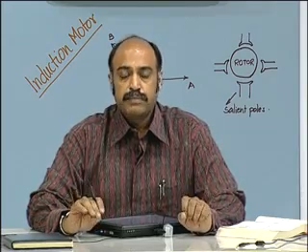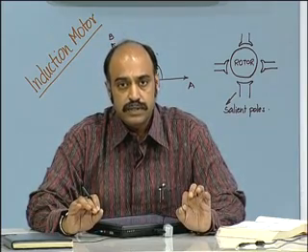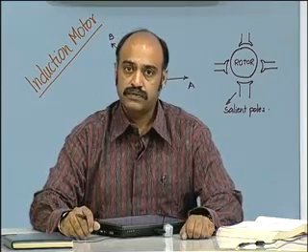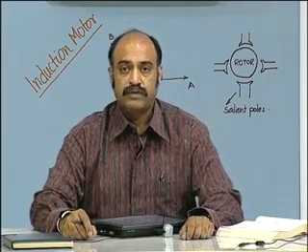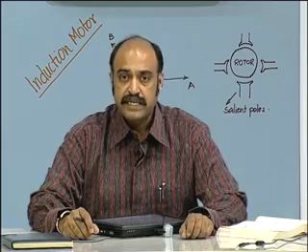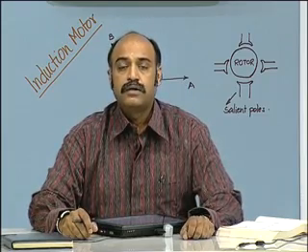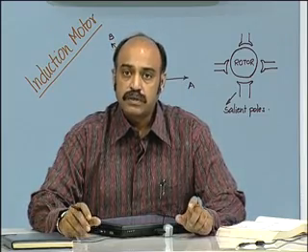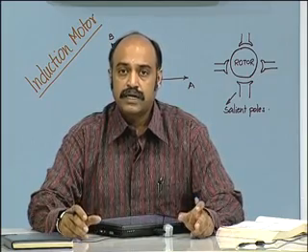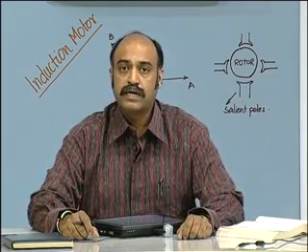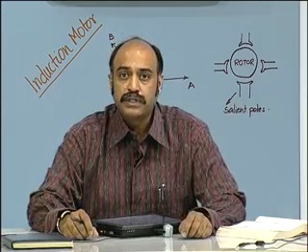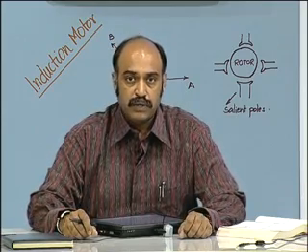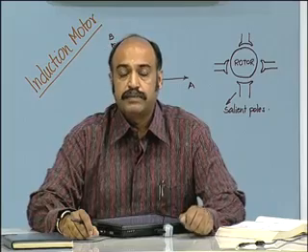And all the working principles and operating principles of the transformers are valid even in the case of the induction motor. You have the Faraday's law of electromagnetics, E is equal to BLV, which induces the voltage on the rotor conductors and thereby a current in the rotor conductors by virtue of the relative motion of the rotor conductors with respect to the field inside the machine.